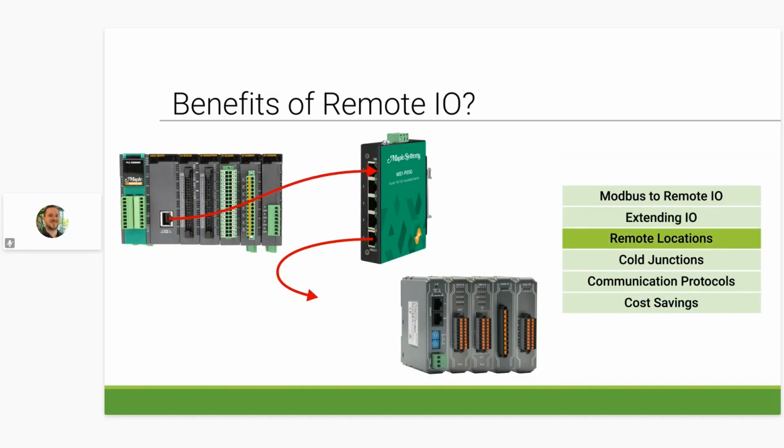As mentioned previously, remote I/O is perfect for also extending local I/O into more remote locations. Given that local I/O is dependent upon smaller and more constrained environments, remote I/O can easily be placed throughout your facility, which acts as an extension of the application, since each remote I/O chassis can allow control of different stations throughout the facility. To further exemplify this, we can look at the use of analog sensors.